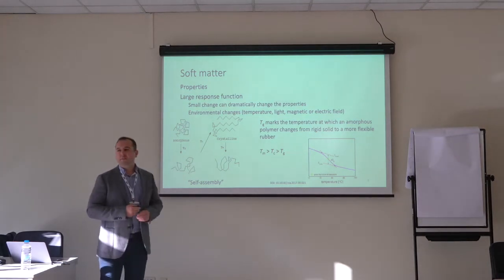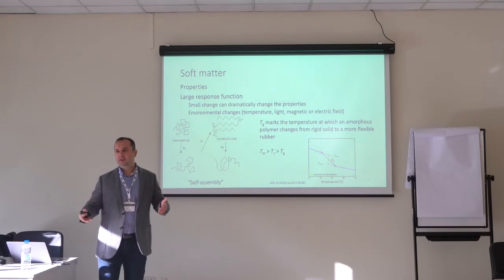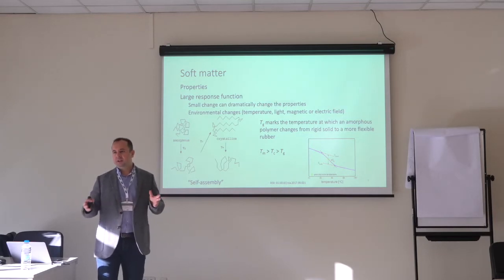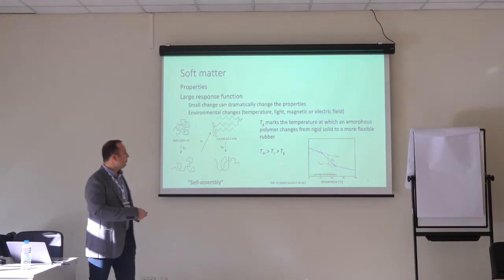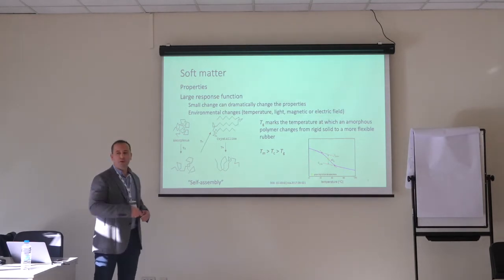The crystallization temperature. That is different from the glass transition already mentioned, because you have limited mobility for the glass transition temperature, but the crystallization temperature is the temperature at which the system switches to a full crystalline state. And the last one? This is the glass transition temperature, so this is how we try to estimate it.